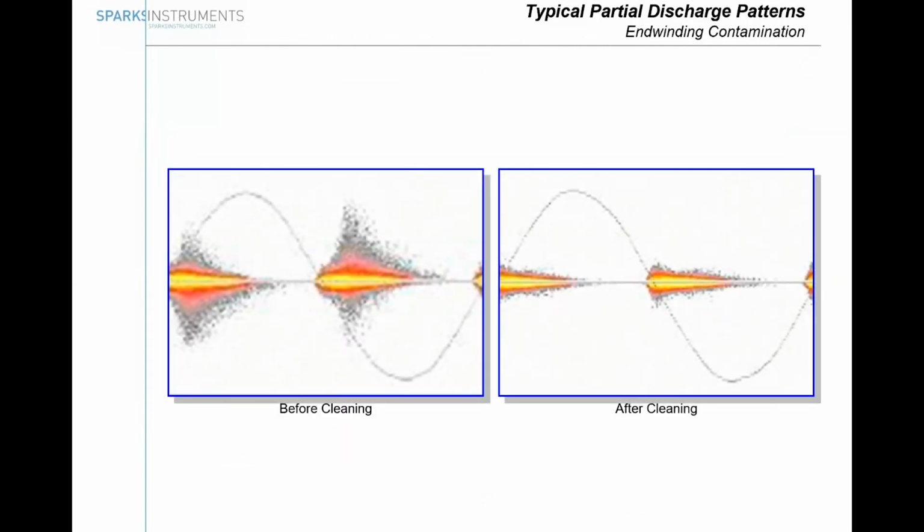Then, for example, an air-cooled machine, in this example, we measure, and we know now from the catalog that when we have a few discharges towards the maximum, that's more an indication of surface discharges. Surface discharges are typically signs of dirt contamination. In this case, we open the machine, we see it's dirty, we clean the machine, and we perform a measurement afterwards, and all we can see is, oh, that's all gone. Okay, perfect, we were right. This is surface discharges, and the rest that we have is internal discharges.